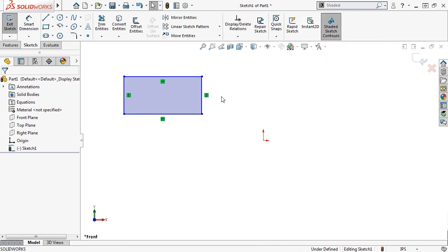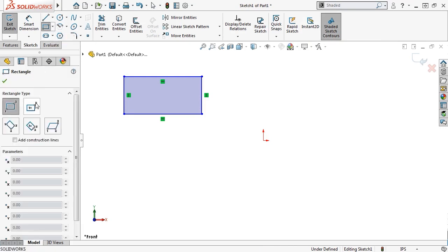You will notice in the Property Manager that you can choose to switch to one of the other rectangle tools without having to exit the tool altogether. If you look closely at the icons, you will see points and a number associated to each point. Each point is a mouse click in the graphics area, and the number is what order the click is in.